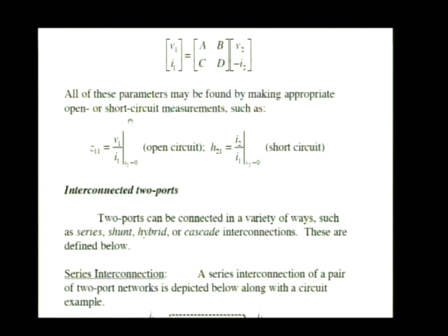What I'm saying is, in order to define these low-frequency parameter sets, and in order to be able to measure the low-frequency parameters, what you have to do to your two-port is either with pencil and paper in a calculation, place a short circuit or an open circuit on port 1 or port 2 and do calculations on the circuit or do measurements on the circuit.